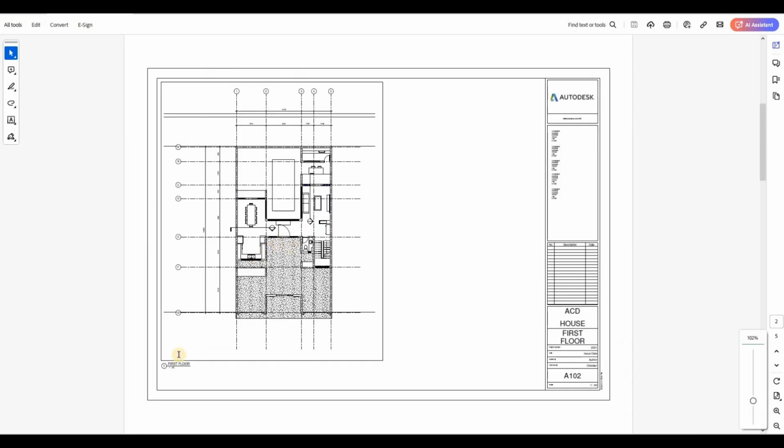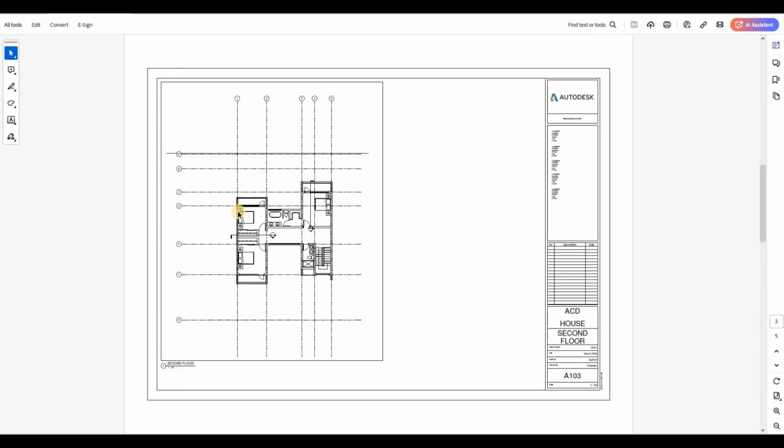After that, we have the first floor. We changed the scale to 1:50, and we just want the name of the title to be changed, not the corresponding view. So that's different ways of doing that. We added some borders as well, and then we created a crop so that it doesn't show anything else. Here we also have the second floor, same idea as what we did on the first floor. We changed the scale, we added border lines, and then we cropped it.